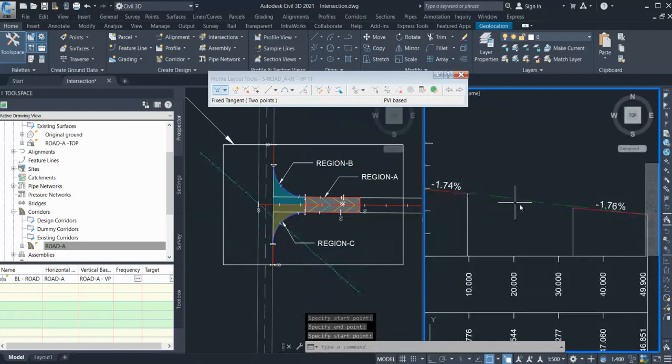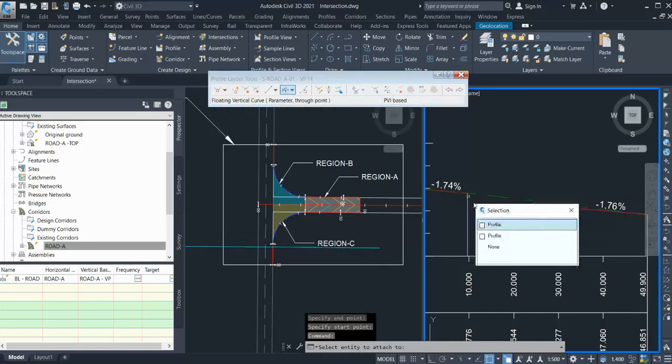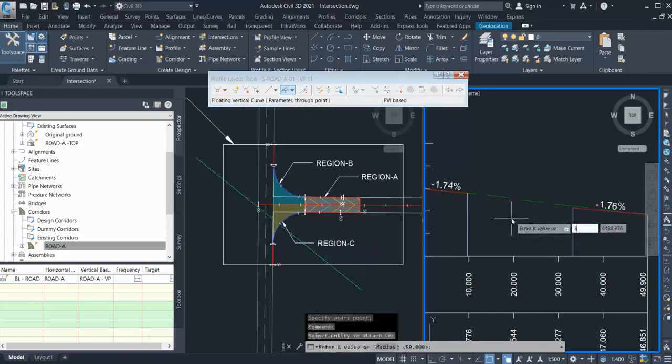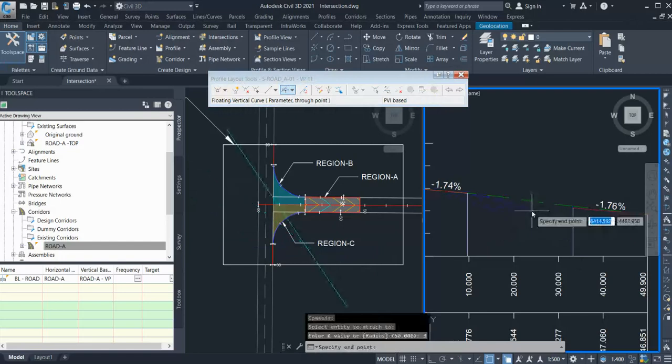Okay, and then you need a curve in between. Now here is a bit tricky to give the curves, simple curve. From here what I'll do, I'll select some floating curve, select this, and give some k value, like give minimum 3, and here same thing.